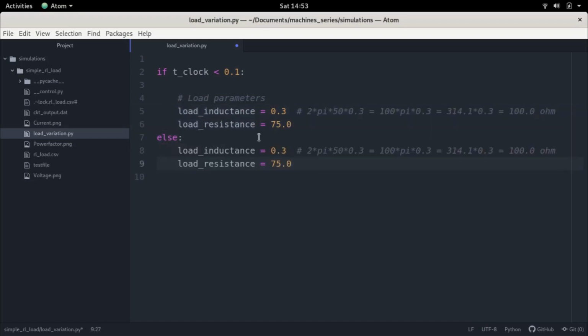So for example, if I come here, let me get rid of this comment. Now instead, let me choose a smaller value. So let's say I make this 0.1, which means now the inductance is much less than the resistance, because this is reduced to around 30 ohms. If it is reduced to 30 ohms, you would see a change in the value of this current.